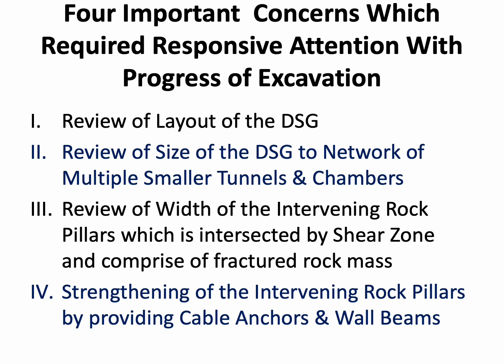So, four important concerns which required responsive attention with progress of excavation in such situations are: first, review of layout of the Downstream Surge Gallery; second, review of size of the Downstream Surge Gallery, changing it to a network of multiple smaller tunnels and chambers. That is how the size should have been restricted, by changing its layout to multiple smaller tunnels and chambers.